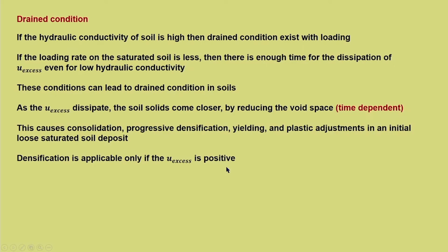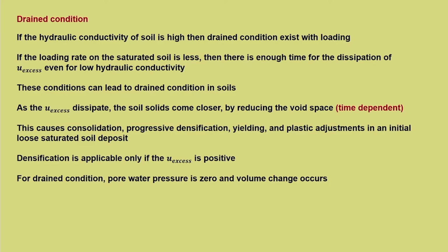Now, densification is applicable only if U excess is positive. Yes, only positive pressure leads to densification. If it is not, what is the other case? U excess can be negative. We will see that later. But densification is possible when it is loose. For loose soil, the excess pore pressure will be positive, and that dissipation causes densification. For drained condition, pore pressure is 0 and volume change occurs.